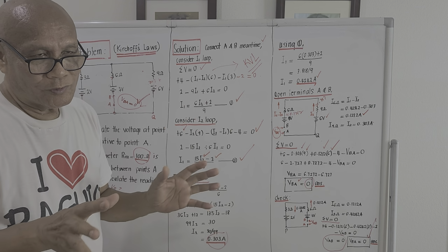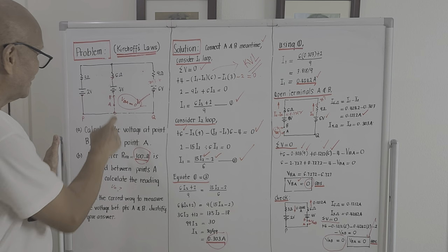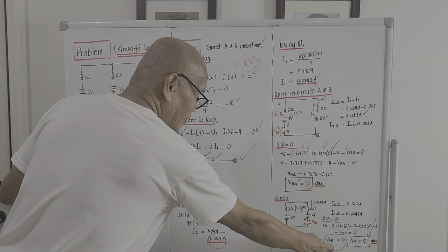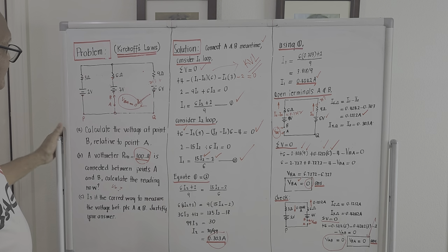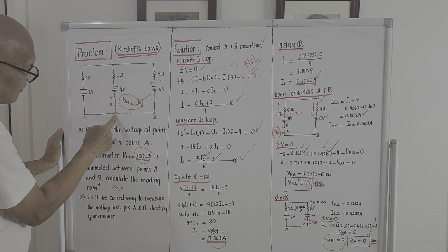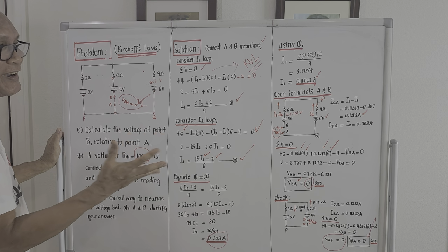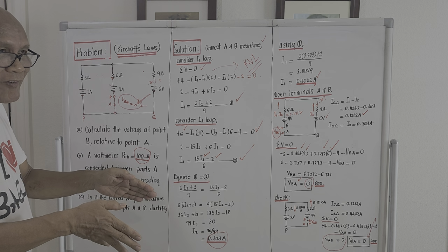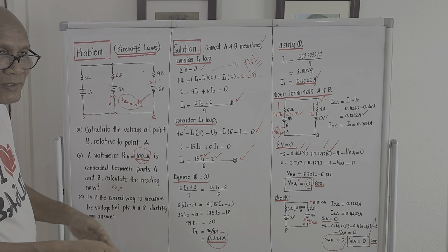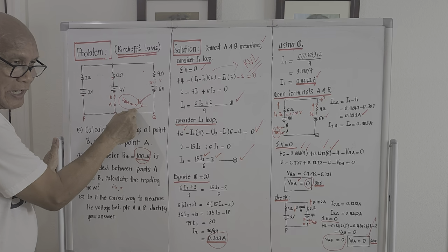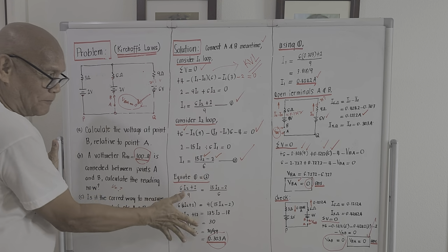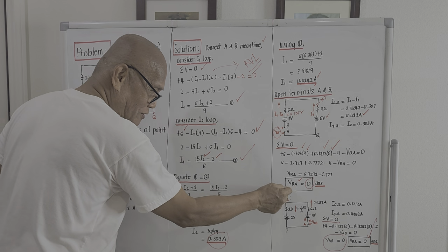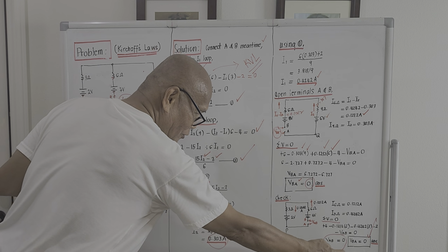So from the problem given to me by Mr. Veracruz, the voltage across B and A is actually 0. That's the first solution. Second solution is still 0. And by inspection, like what I said, this is ground and this is ground. So we are taking the voltage across the same terminal. So if we try to get the logic of that one, the voltage should be equal to 0. And we have proven it by applying Kirchhoff's voltage law that the voltage across B and A is 0. This is the second solution, V sub BA equal to 0.